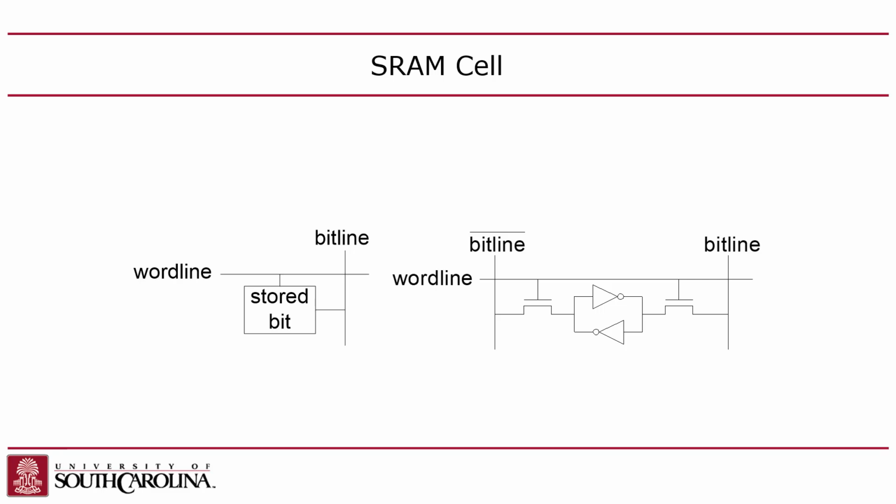Now, what's the difference here between the SRAM and the DRAM? The SRAM has two inverters, right? How many transistors are in an inverter? Remember, there's always two transistors per input. An inverter has one input, so there's two transistors here, and then you need two transistors here. So that's in total 6 transistors per bit.